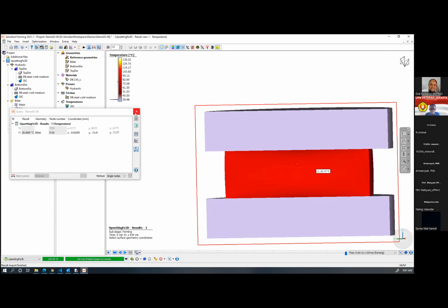But when you talk about element technology, we have two element technologies, hex and tet. These two are the element technologies that SIMUFACT will be using. When it comes to sheet metal applications, SIMUFACT also has a solid shell element approach, where it takes a solid element, not a shell element, but it creates different layers inside the shell element. It's a hex with a solid shell.